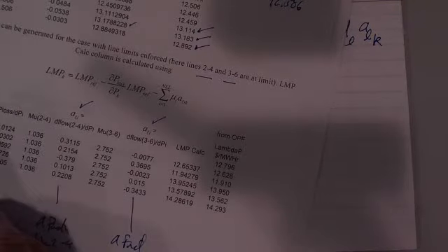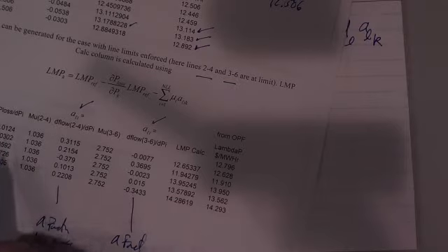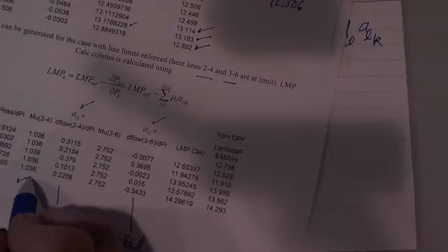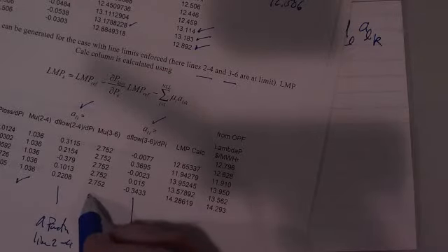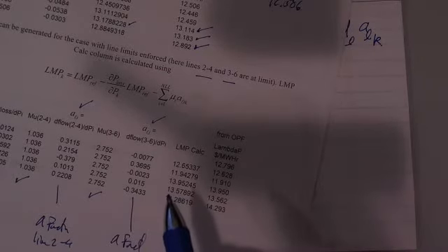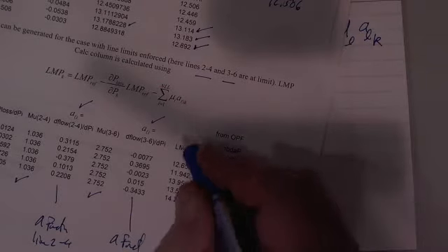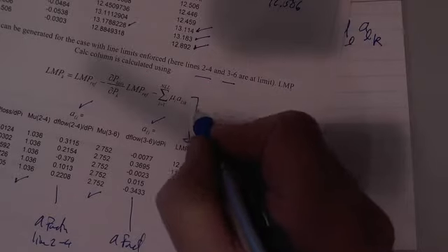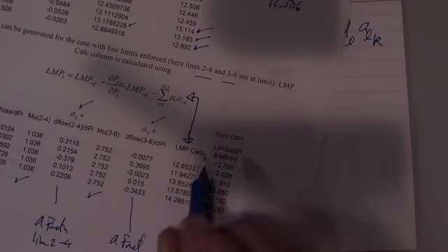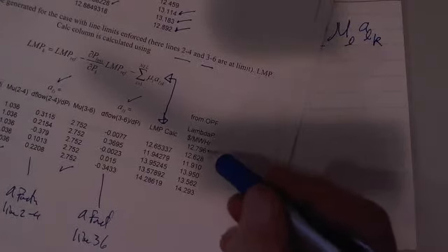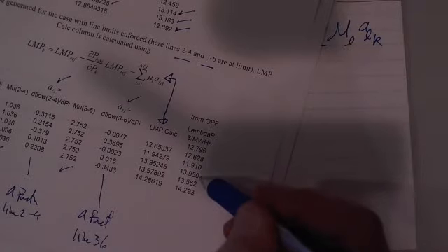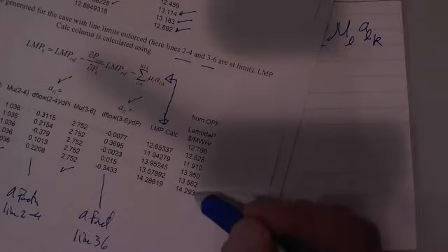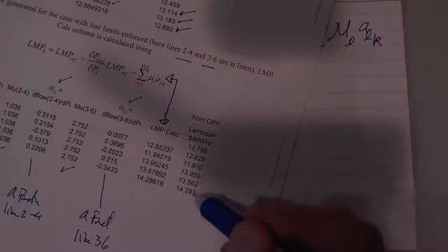And here's my lambda for the reference bus, the incremental losses, and now here are the mu factors that it gets out of the optimal power flow. And I went all the way through and I calculated this from this formula that we developed before, and I compared it to the lambda values that we got from the OPF itself.